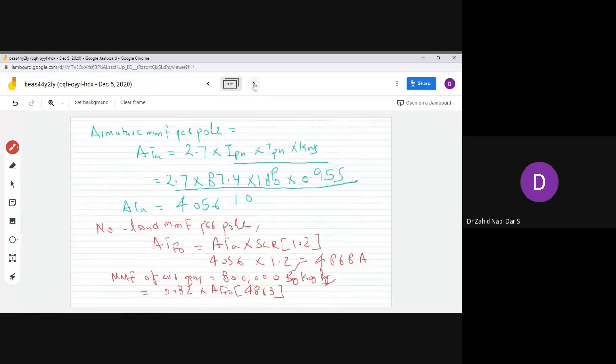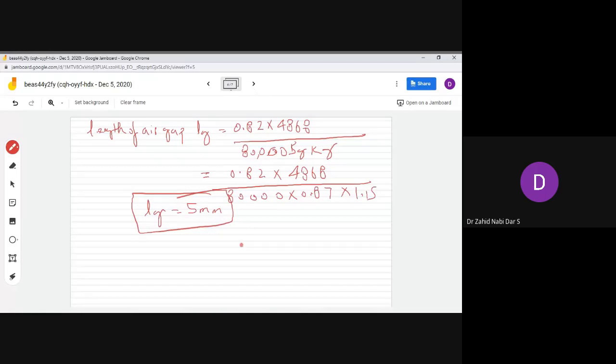No, see, basically what happens is there. I'll just explain you here. KVA means KVA of the machine. If you are writing in terms of phase quantity, it would be 3 V phase I phase. But you are writing in terms of line quantity. So there it is root 3 V line I line. This is the KVA of the machine. So if you notice, the V line value is given in terms of kV value.